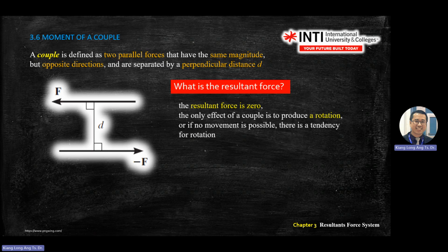This is important in screw design, especially in aerospace. The thread direction in which you screw and unscrew is important because vibration happens on the spacecraft, and if you're not careful, the screw will unscrew itself and loosen the part. So in aerospace, we usually don't use threaded screws. We use rivets to fix things. Okay.